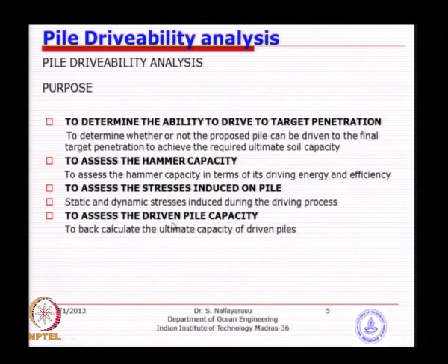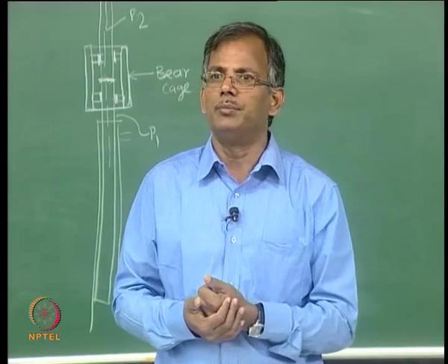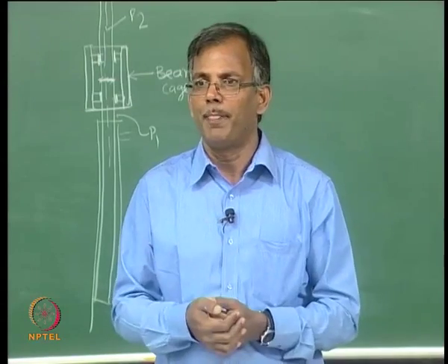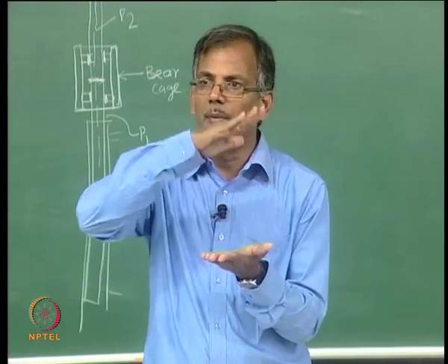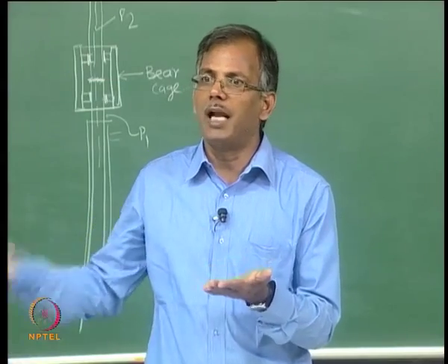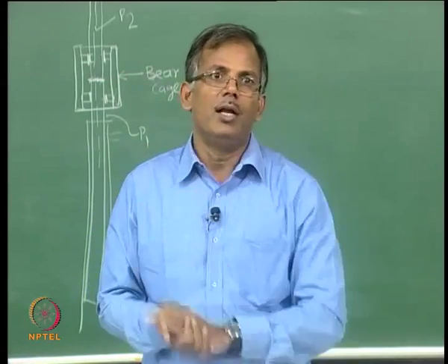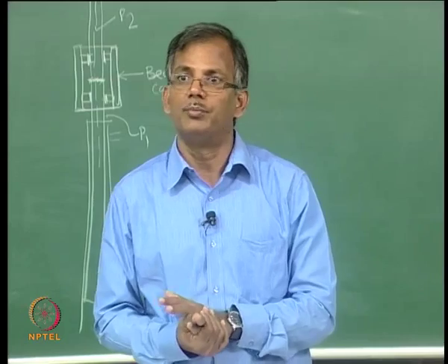The last one is also very important, since we could not do any more testing because of water depth, because of the capacity, because we may require 1000 tons of capacity, we cannot do a test. For example, most onshore systems may have 100 tons, 200 tons capacity. Normally, you might have seen in the pile load test, they construct a frame on top of the pile and place a lot of sandbags, or big concrete blocks.